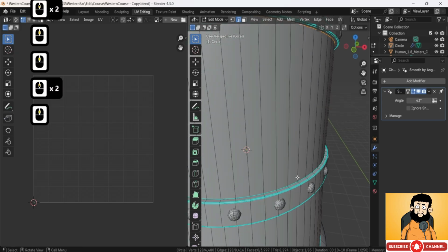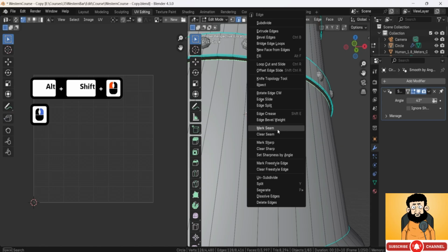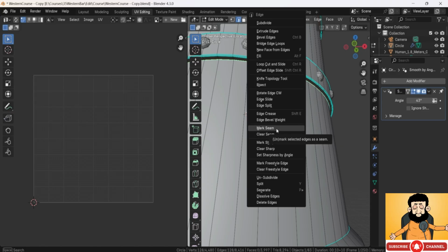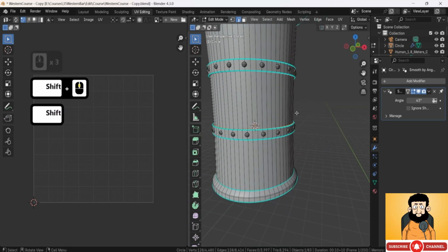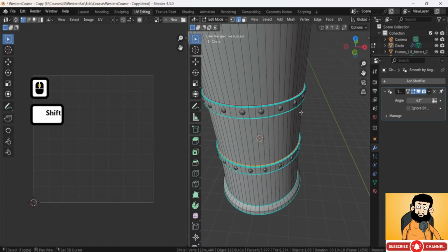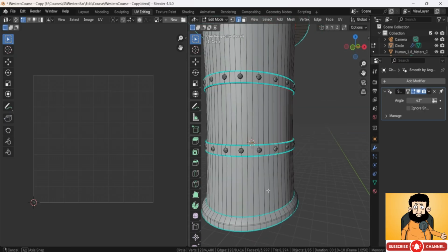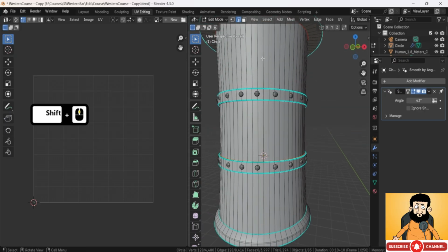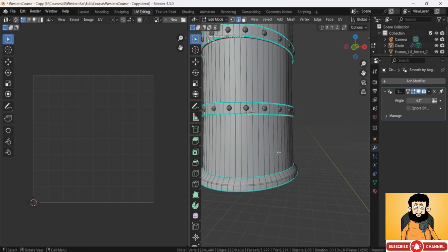I'm going to do it for the upper and the bottom part because they're going to be separate objects, separate material that is, and it's just going to avoid any unnecessary UV deformities. So mark seam. I always think about when doing this how many pieces it is going to be as well. So for example, this entire cylinder could technically be just one massive piece, but at the same time, splitting them off onto 5 different parts is still not a big deal, especially when using seamless textures. Still totally okay and fine to make use of that.